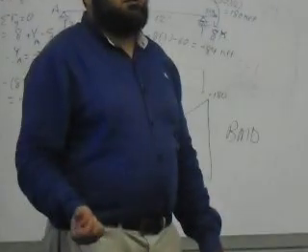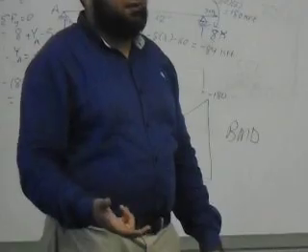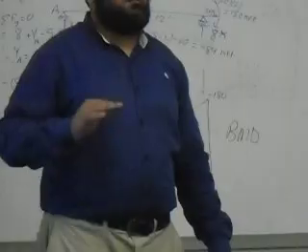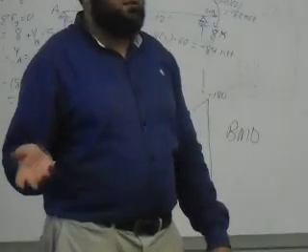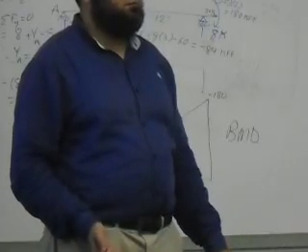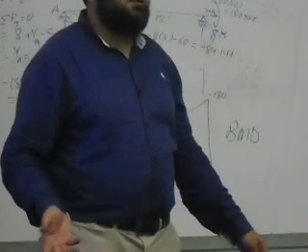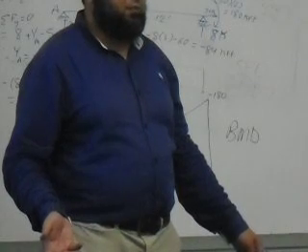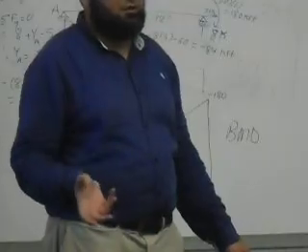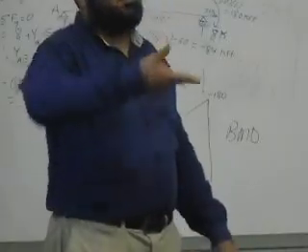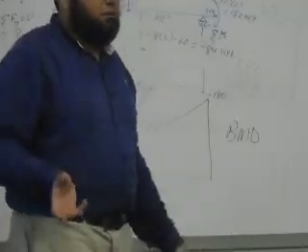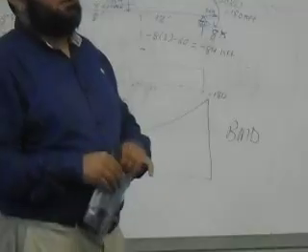However, in North America, they use the convention that the negative is down and the positive is up, because simply speaking, they are designing steel members in most cases. But designing a steel beam, it doesn't make a big difference whether the moment is positive or negative, because you are designing it as a member, as a whole, and you will be placing the I-beam. You are not reversing the I-beam. You are just placing the I-beam as is. Okay? If you are talking about a standard section.